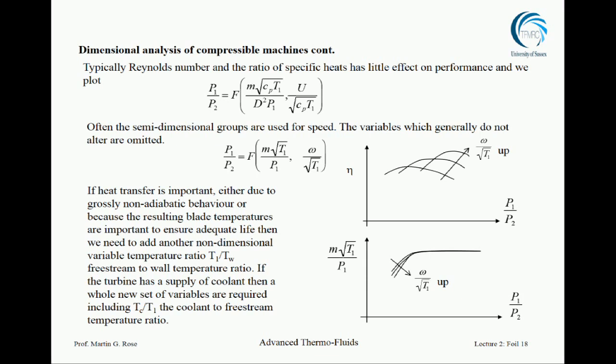If, however, we run at particularly low pressure ratio, as the engine does when it's starting up from idle, things start to change. The capacity drops off and the curves depart one from the other because the rotational speed is changing. And if the rotor's going faster, the capacity is lower. If the rotor's going slower, the capacity is higher. So that's the tale of capacity in a turbine.